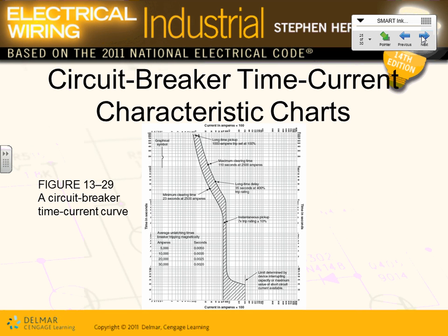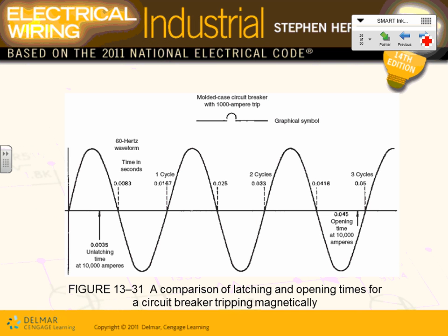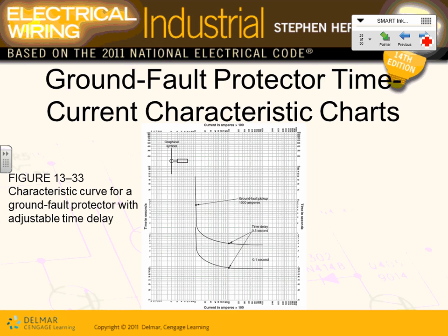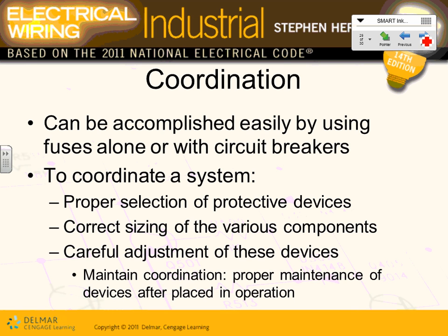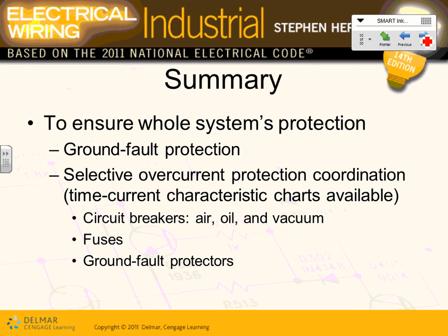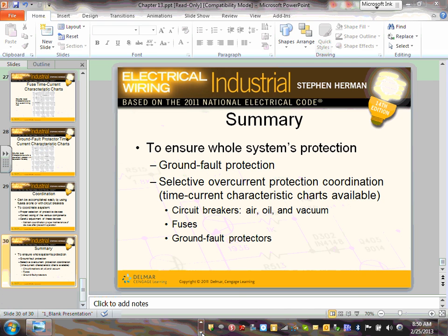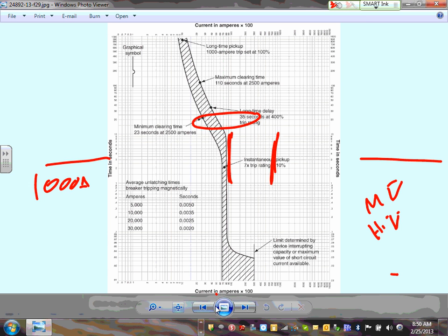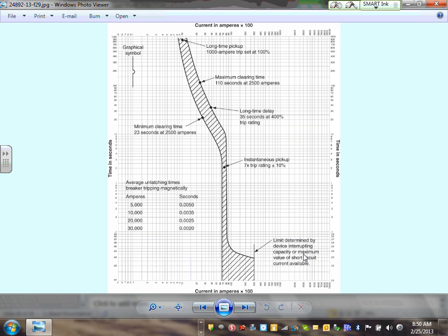Okay, the last thing I want to talk about, guys, is the overcurrent protection device, time current characteristic curve, and a couple of these curves that we're going to do, and coordination, localization. So I want to get rid of this and go to a couple of pictures and show you. The second thing, guys, on our agenda to do is time current characteristic curve. This is you guys going to be doing this one next week with SKM.